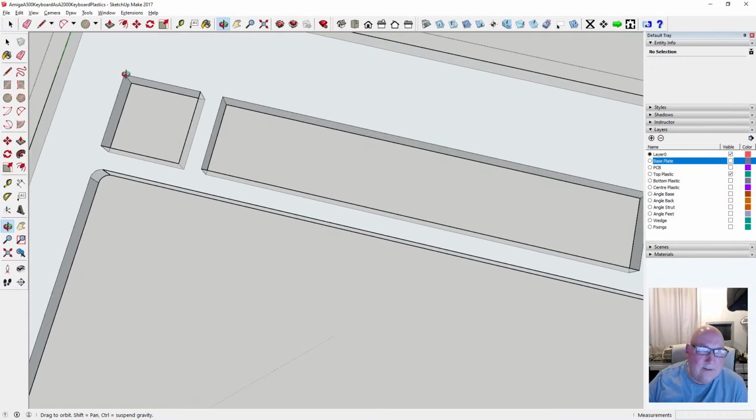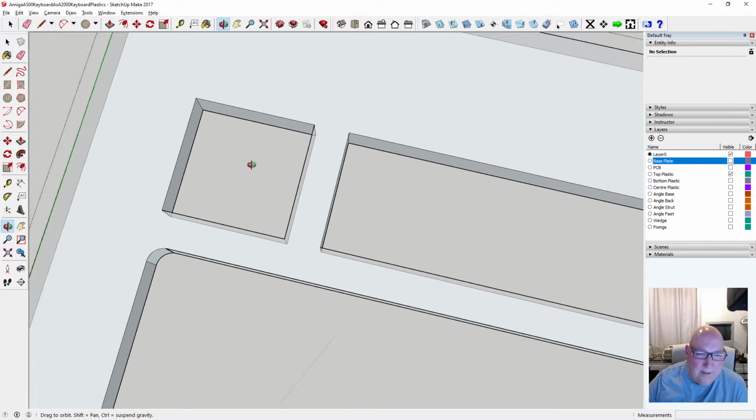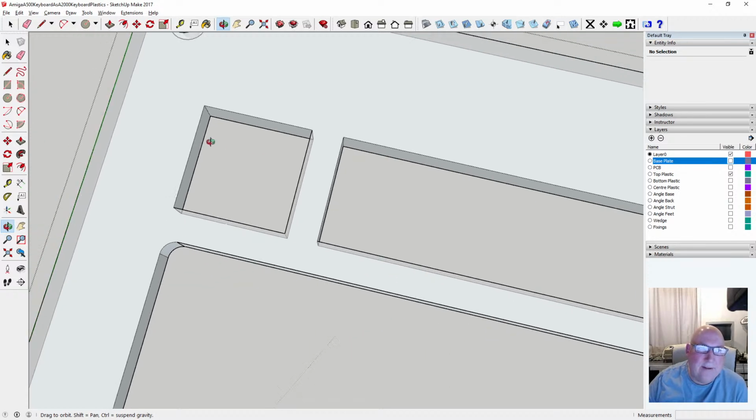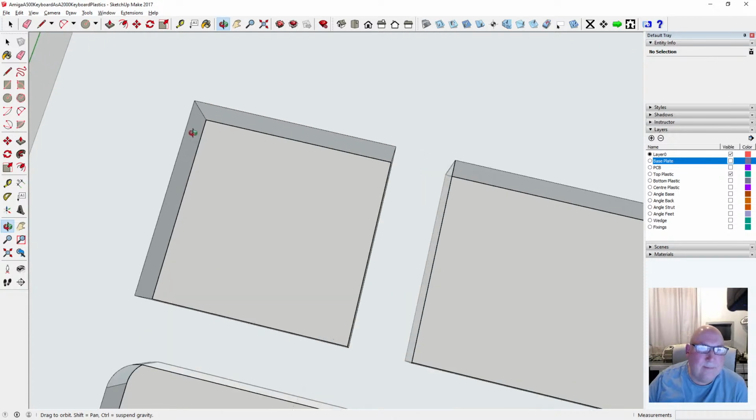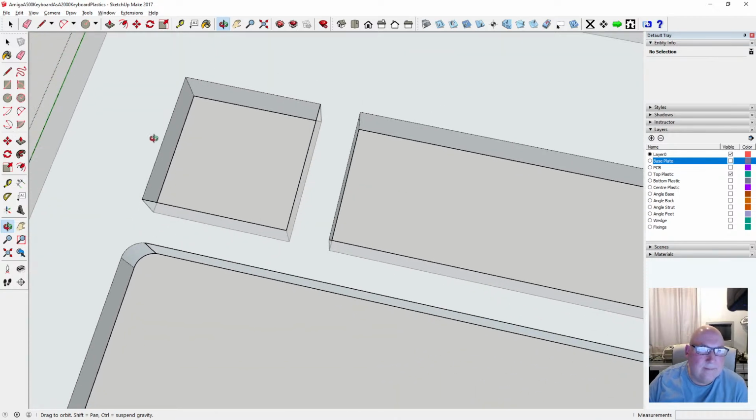Got to have it because I have trouble milling out. If I create the G-code without it, the toolpath will have the CNC go up to here, and it'll go boom, bang like that. Then it'll do one, and depending on when it came down to do the first one, it'll be a different shape to the rest. But if I put a bend on it, they're all going to be the same shape, basically. Pretty much.